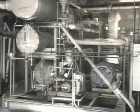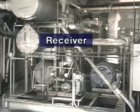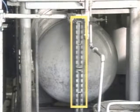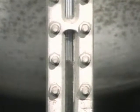There are also level indicators that should be checked. Two common locations for level indicators are on the receiver and on the oil reservoir for the compressor's lubrication system. The level indicator on the receiver monitors the amount of refrigerant in the system. The proper level of refrigerant must be maintained in the receiver to ensure that an adequate supply is available.